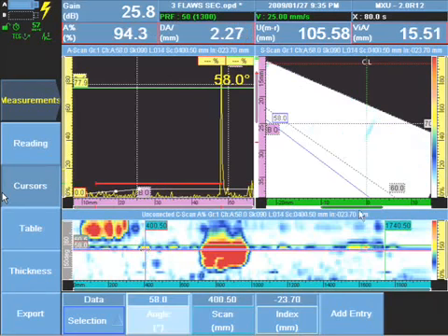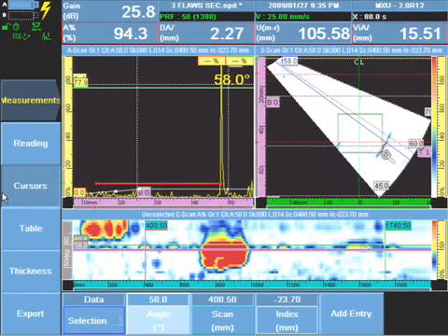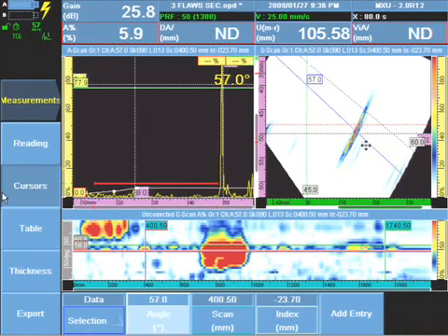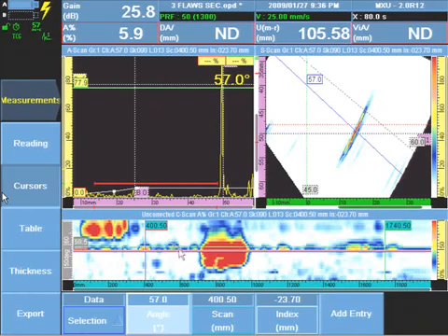Here we have an indication plotting directly to the cap on the end of our second leg. We have the first skip B0, the end of the second skip T1, and we have an indication very typical of cap geometry plotting right to T1, typical throughout the C-scan.